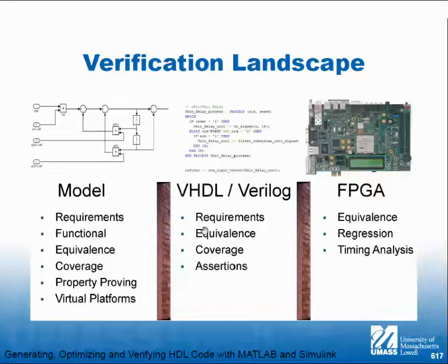Our HDL, so again, requirements, again, equivalence, because it's another model. We can get coverage of this, and the coverage is more applicable because now we're looking at the exact code that we're going to synthesize, and we can also insert assertions. Remember, assertions are things that tell us things about the code while it's running in simulation, and then ultimately we can put it into an FPGA.